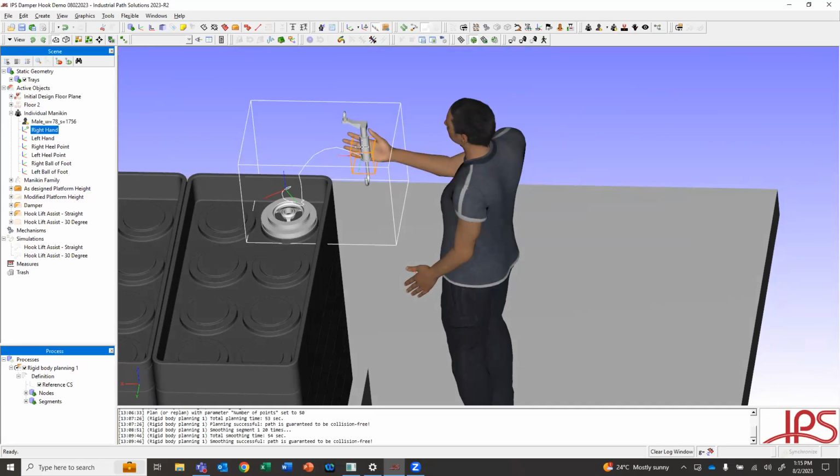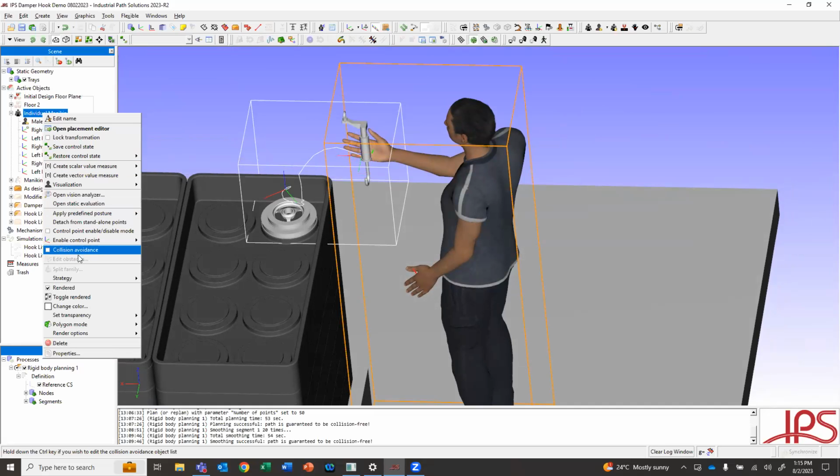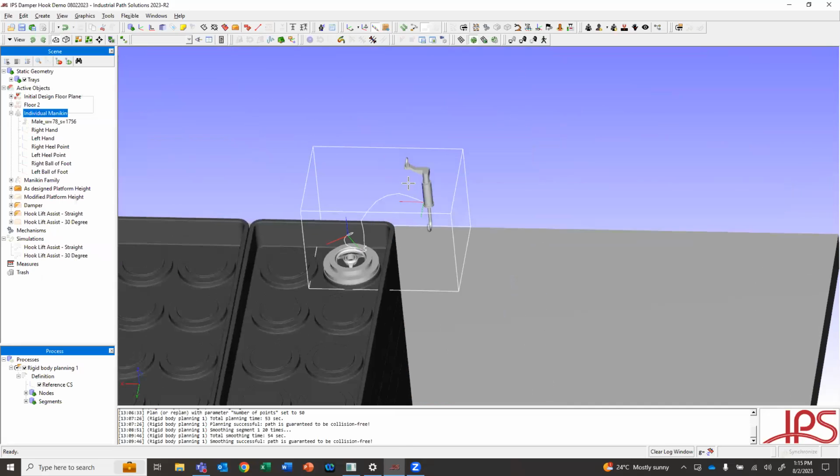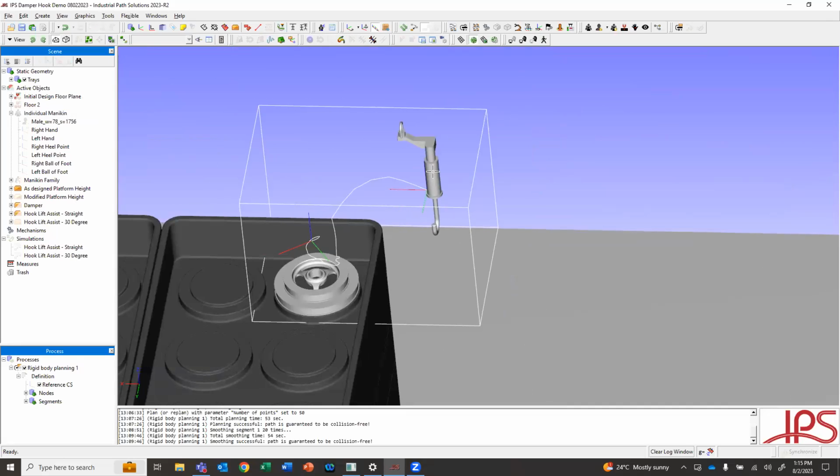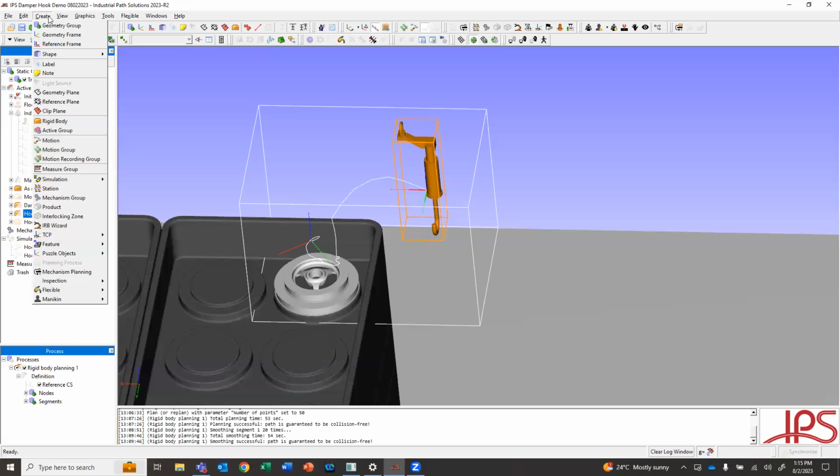If I wanted to create a grip point, all I would have to do, and I will hide the mannequin here just so we can see it a bit easier, is select this hook that we want them to grab. And then I can either select here in the create grip point, or I could go create and under the mannequin section, grip point.